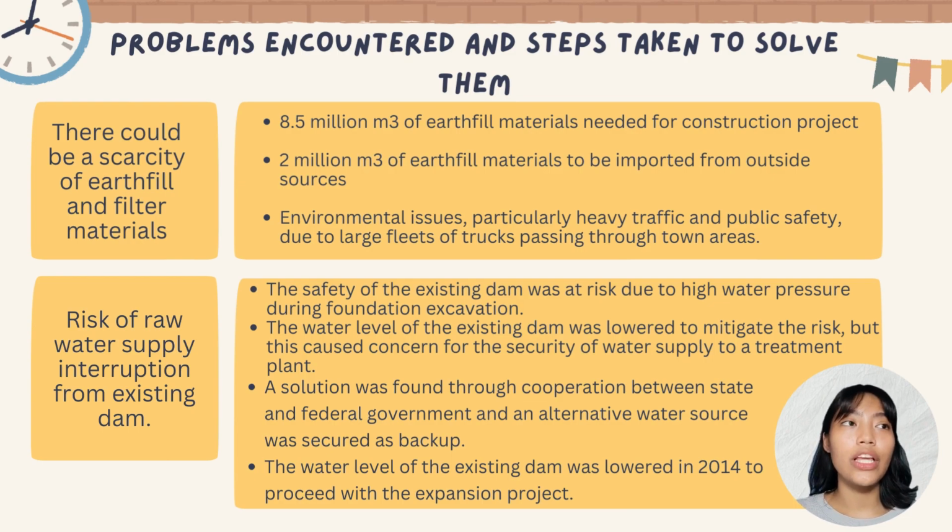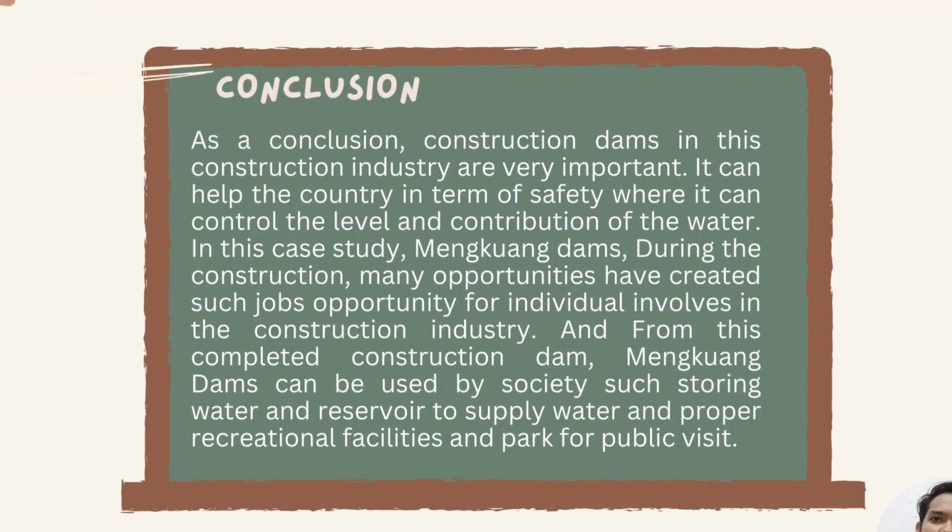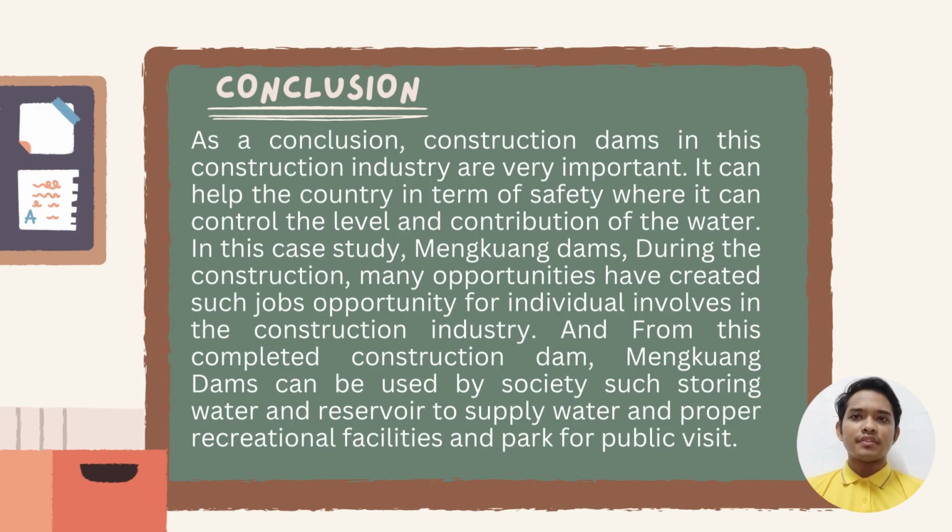The next problem is that due to rock mining at the quarry, there is a risk of leakage at the new dam's left abutment. Heavily jointed and sheared zones in the rock mass facing the quarry were identified as potential leakage paths for the dam reservoir. Several tests were conducted to calculate the risk of the leakage. Due to these tests, measures were taken such as variation orders to help resolve the risk of leakage exiting the excavated quarry face.